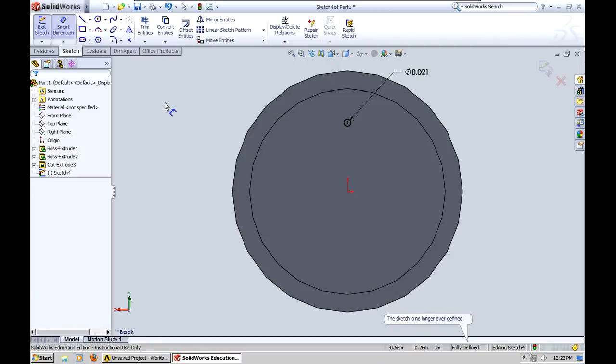The biggest reason why is because when it comes down to calculating things like the mass flow at each of the inlets and how much power in latent energy is going through, every fuel has a lower heating value and a higher heating value, and based on those numbers you have to decide how much fuel is going to go into each of the nozzles by doing a teeny bit of thermodynamics.